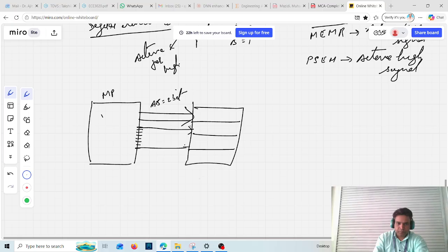So this is the data bus, and it is 8-bit. And then we have a control bus which is 1-bit. Now, please try to understand why this address bus size is 2-bit: only 2 bits will be required to assign the addresses to the different locations.